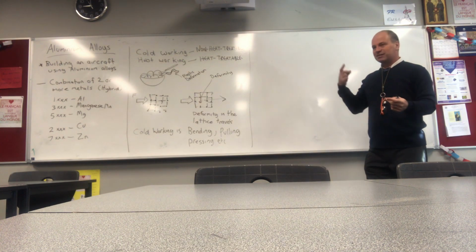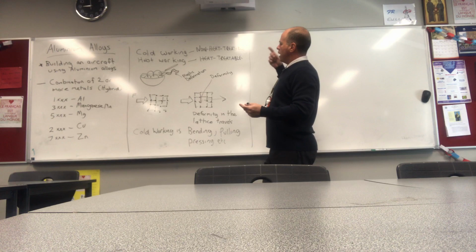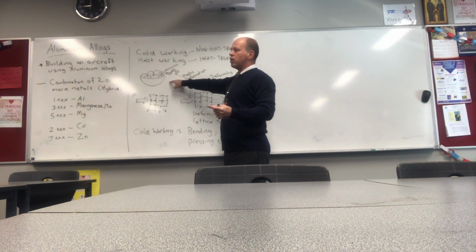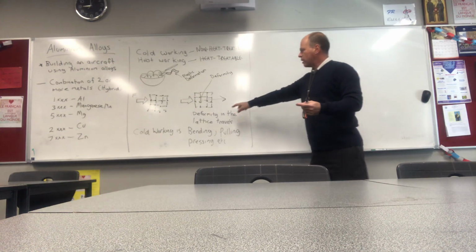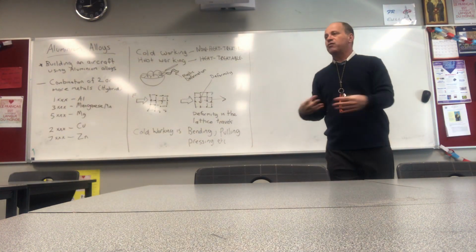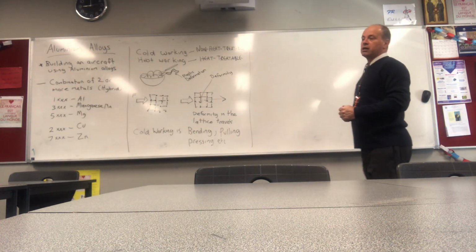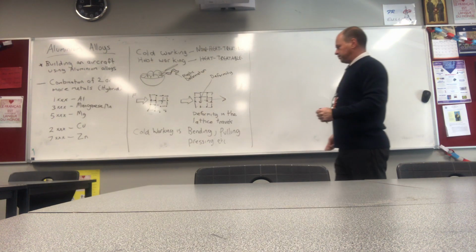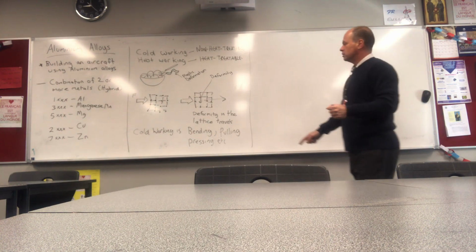That's one of the theories. There's a few theories online that you'll find, but I think that's a really good one. You start with this idea of a macro deformation, and then we go to the micro, and we talk about deformities travelling, and if you've got enough of them in a small enough area, you get a harder material, okay? So you've just got to remember that that is the basics of cold working, and we will watch the video to get an idea of it.